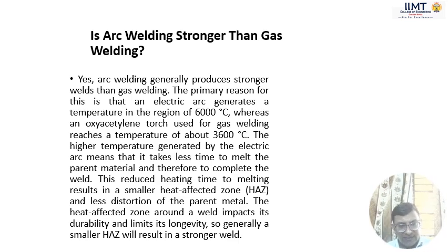Then there is less distortion to the parent material. The heat affected zone around a weld impacts its durability and limits its longevity. So generally a smaller HAZ will result in a stronger weld. This is the reason we can say that arc welding is stronger than gas welding.